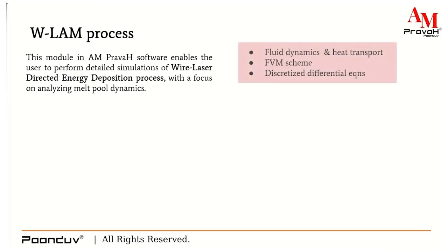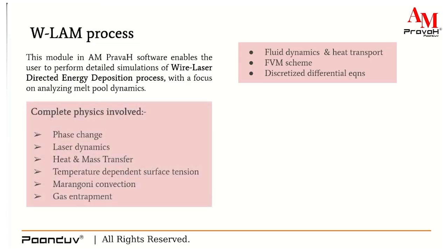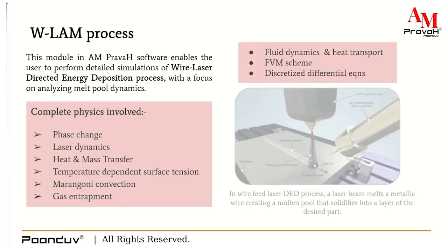So it mainly solves equations for fluid dynamics and heat transport, and it uses the FVM scheme. It's a finite volume method scheme to solve the discretized differential equations, and it also captures the complete physics involved, that is the phase change, laser dynamics, heat and mass transfer, temperature dependent surface tension, Marangoni convection, and gas entrainment.